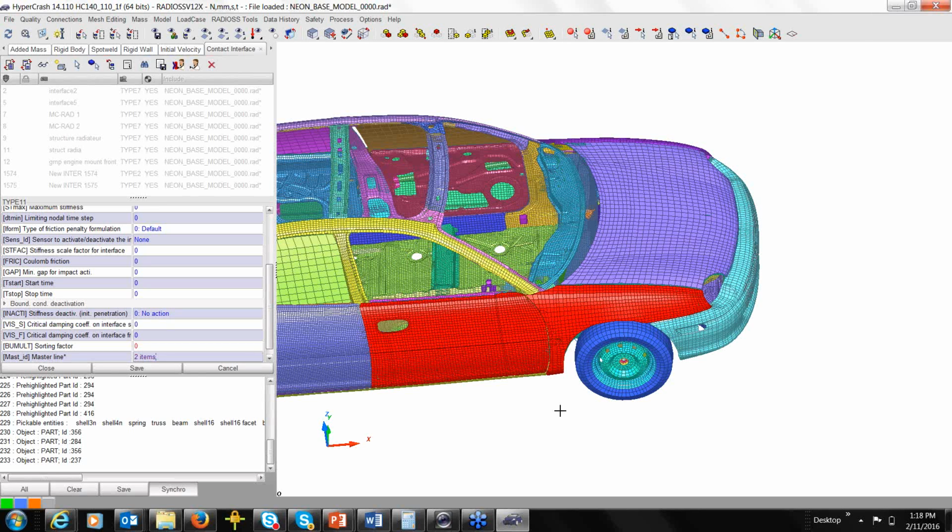If you are proficient in HyperMesh and you were to create your model in HyperMesh, if you deal with a type 7 interface, you need to have a physical skin on the solid element, because the way the interface works is, since it's a node to segment, there's no such thing as a segment surface on the 3D solid.